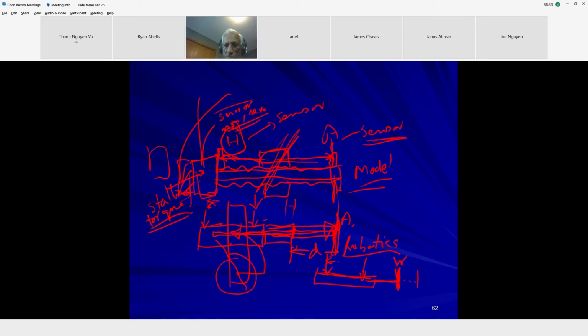And knowing the way the air works, let's say this cylinder is capable of taking up to 30 psi, and I have a line pressure of 120 psi. I can go up to 120, but 30 is good enough because let's say this is a small cylinder. So I apply 30 psi. That's the pressure applied to this air cylinder, and it's advancing, and I want to maintain here. Will it stop? No, it'll keep going to its maximum distance.